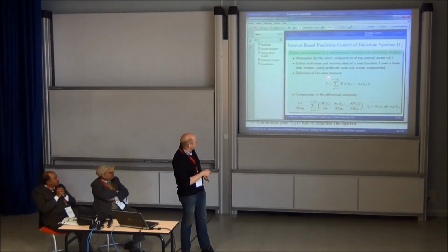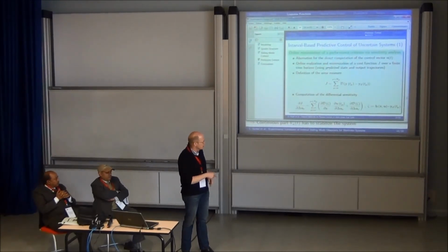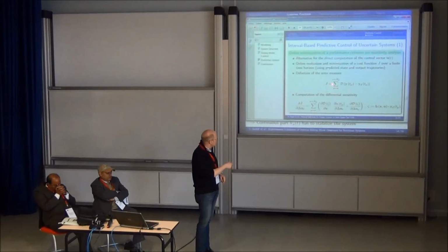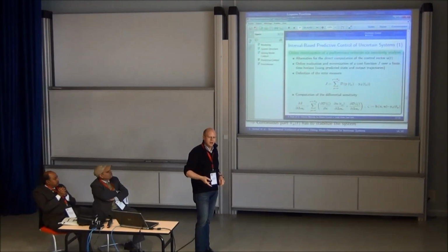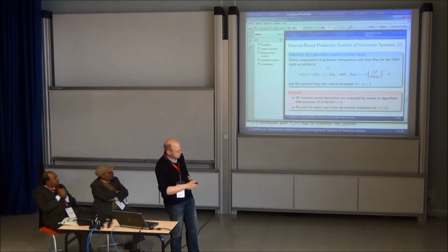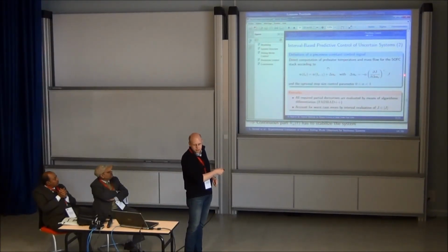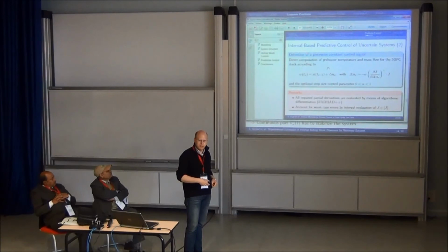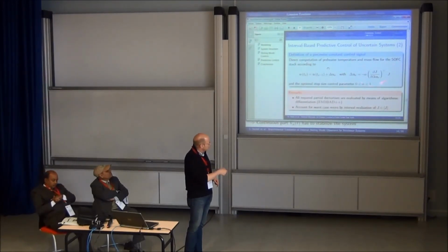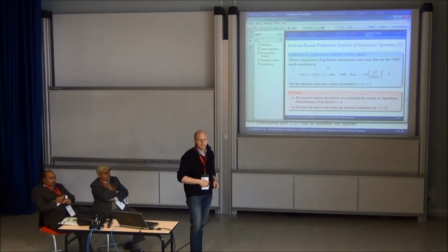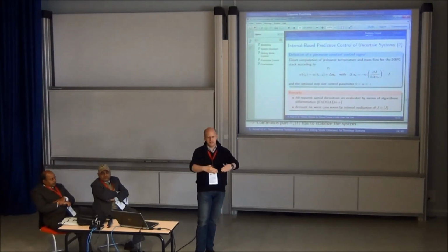What we want to do is make this J, which afterwards is an interval, as small as possible. That means what we are implementing is something like a gradient search. We're searching for the steepest direction in which we can reduce J, the supremum of J. This is done by this pseudo-inverse scheme. We just plug in, on the following slide, this interval pseudo-inverse in the round bracket. We have an interval for J, and then the heuristic search for this gradient method is to take the supremum of the complete term on the right-hand side. Okay, so it's worst case. It's something like a worst-case gradient search.